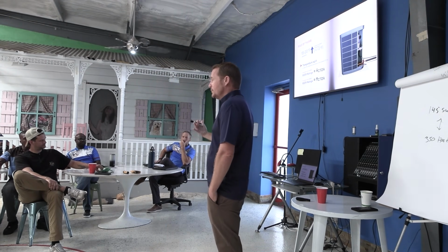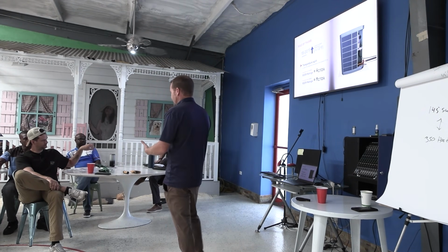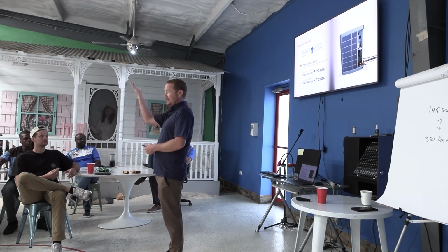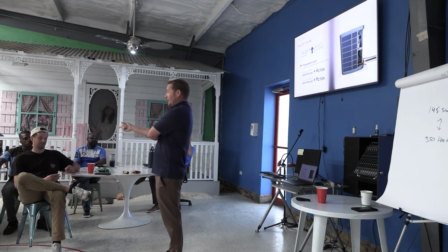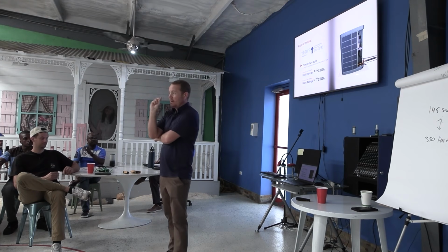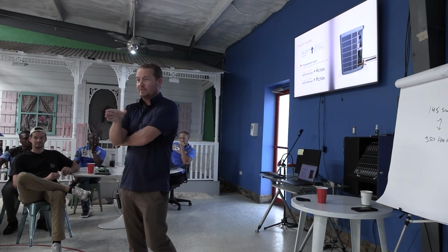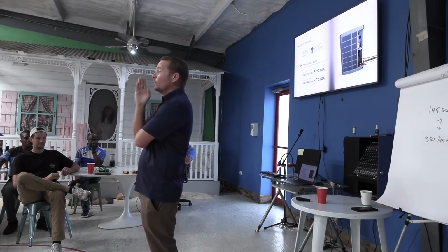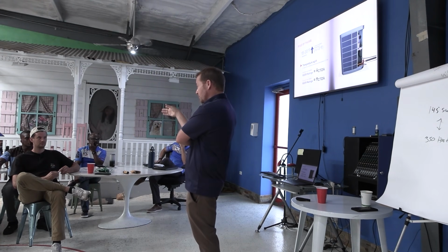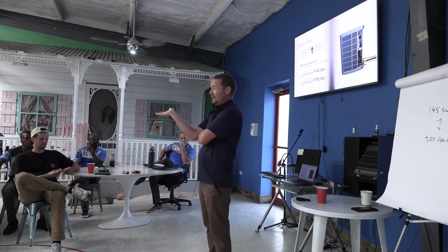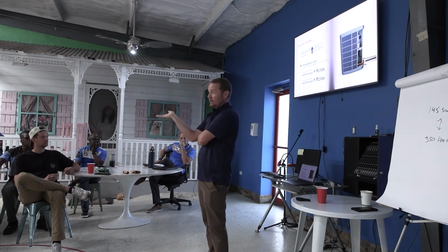So when you go up to a system and you're looking at your condensing temperature and it's significantly higher than that, what do you know? You know something ain't right, right? I was looking for simple here. Something's acting weird. And so you've got to couple that together with other information. But to Jerry's point, it's almost always a dirty condenser. That's really what you're looking for.